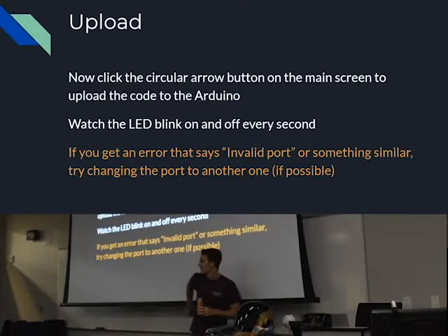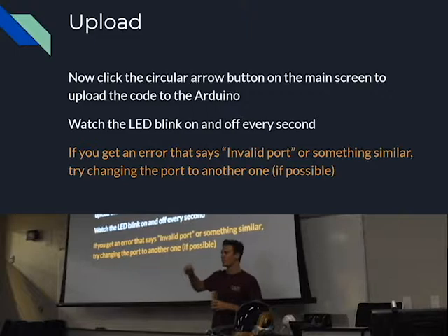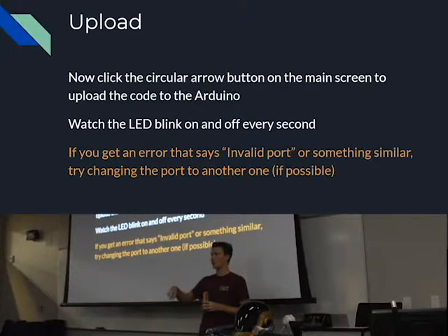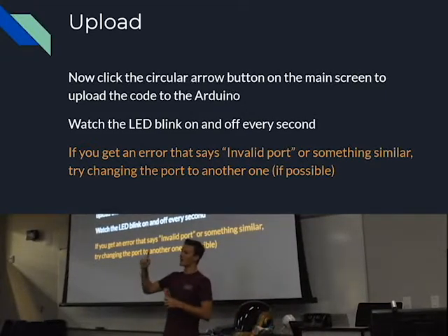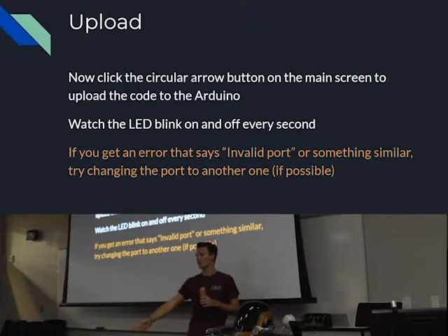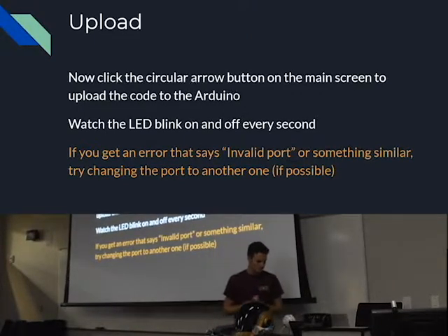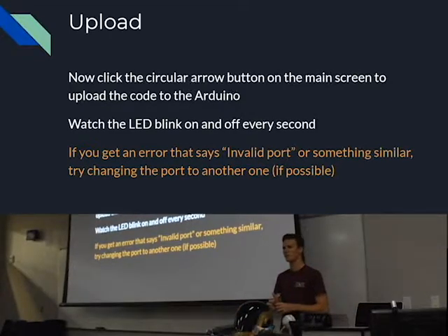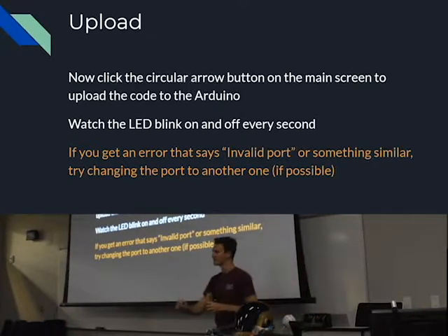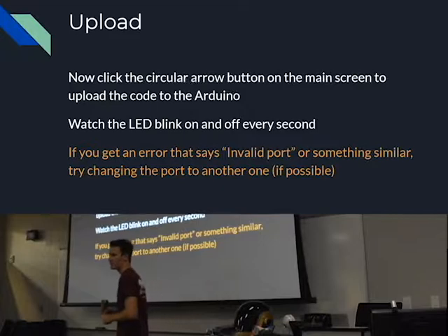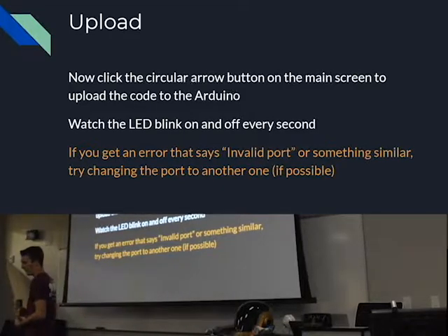This is saying, for the pin that is connected to the built-in LED for the Arduino, create that as an output. So whenever I talk to it, I'm saying, hey, either output or stop outputting. I'm not going to register any input from it. There are ways to make a pin both, but that gets really complicated and things usually go wrong very fast, so it's best to keep it either input or output. And that's basically all that is there in the setup.